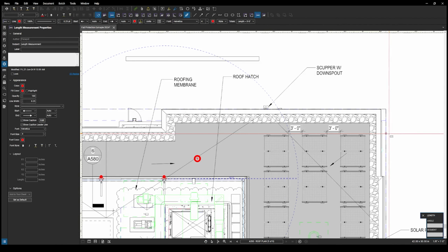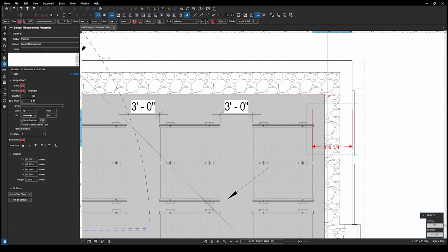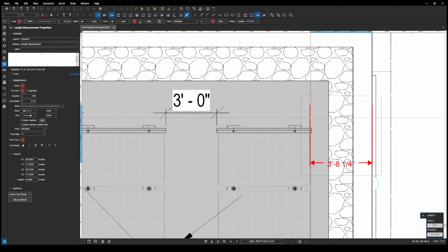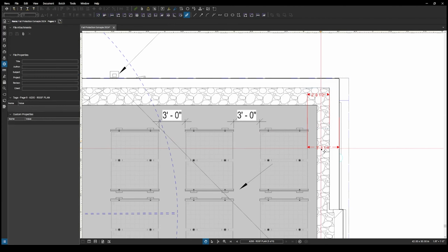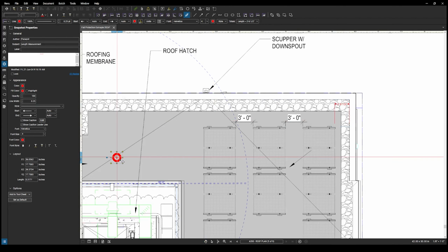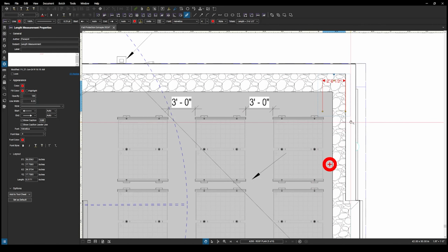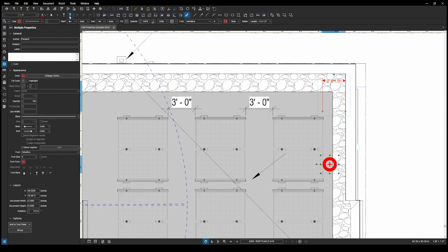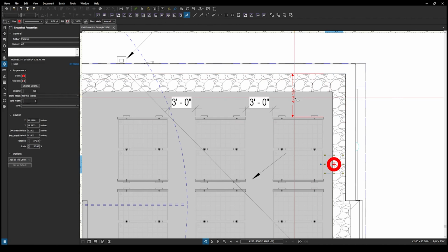Sometimes, in rare cases, if you're lucky, clients are understanding and can condense the spacing and give us a bit more room. But for this case, let's assume we already had the conversation and the client said, no, we can't really move that equipment. That being the case, we're just going to first take another measurement. And now we know that we have a 4-foot clearance between the edge and the solar panel. Our equipment can be as close as 18 inches away from any actual building obstruction to allow for proper waterproofing or weatherproofing, things like that.